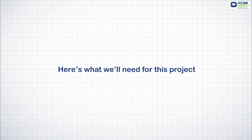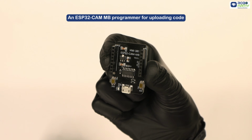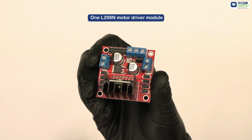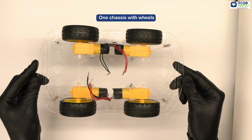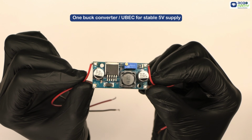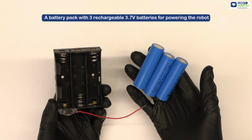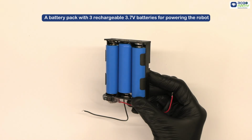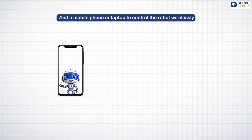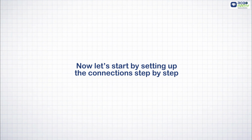Here's what we will need for this project. An ESP32-CAM module, an ESP32-CAM MB programmer for uploading code, one L298N motor driver module, one robot chassis with wheels, two servo motors for pan and tilt movement, one buck converter UBEC for stable 5V supply, a battery pack that is 3.7 volt rechargeable batteries. We need 3 batteries for powering the robot, some jumper wires, and a mobile phone or laptop to control the robot wirelessly. Well, let's start by setting up the connection step by step.